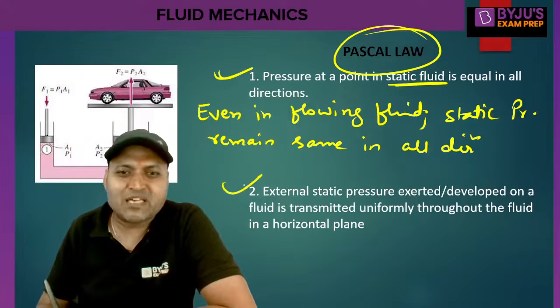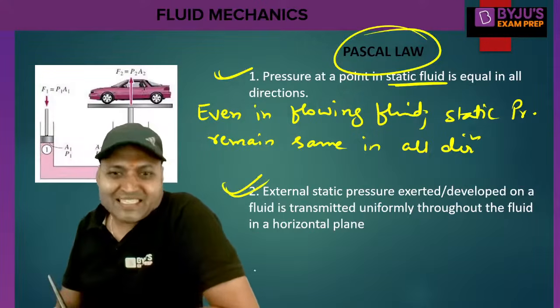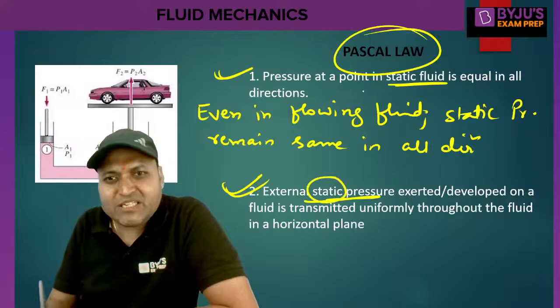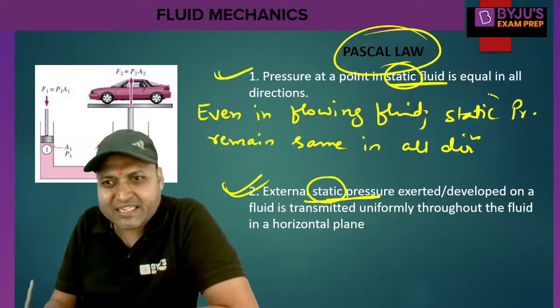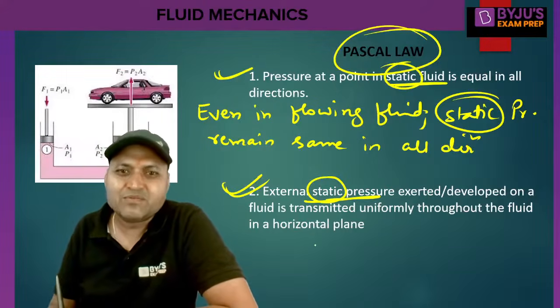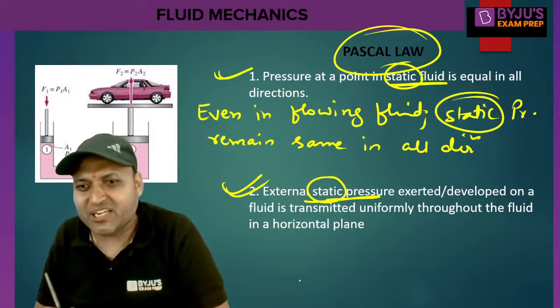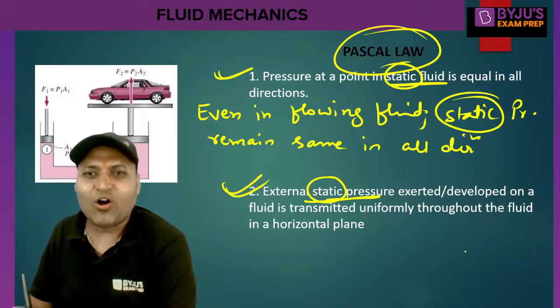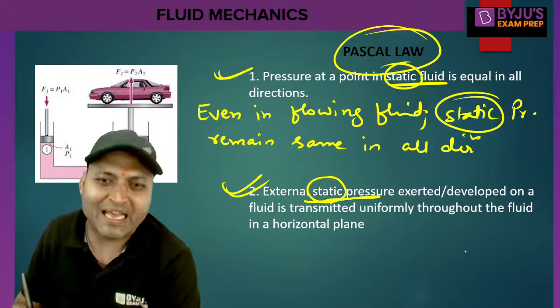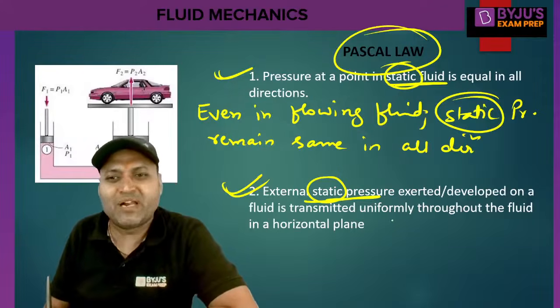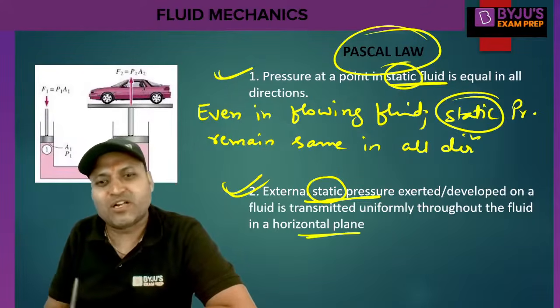Another statement of Pascal law: the external static pressure, it is always about static fluid. The static word is important for Pascal law. The external static pressure exerted on a fluid is transmitted uniformly throughout the fluid in a horizontal plane.